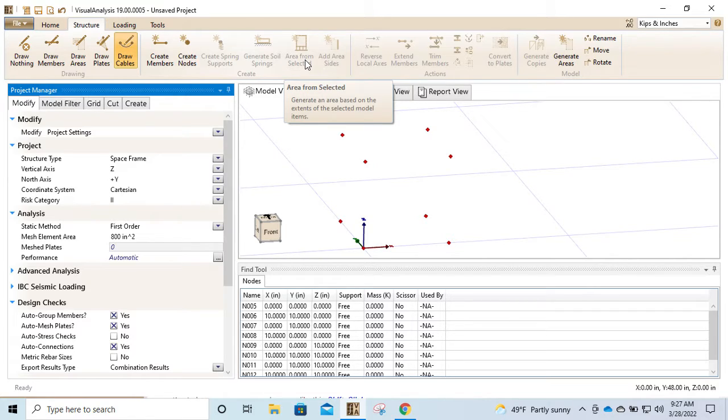have you guys dealt with side plate systems? Have you heard of side plate systems? Okay, it's a proprietary system that for a moment frame, instead of doing, like in advanced steel, reduced beam sections, RBS, where you do a dog bone, essentially, in a moment frame, in say higher level design like special moment frames, we as designers want to make sure we know exactly where the hinge is going to be, and we want to make sure that hinge is in the beam and not the column. Strong column, weak beam behavior. So what do we do? Well, we trim the flanges down.